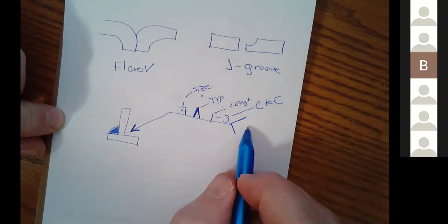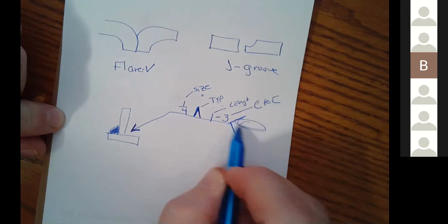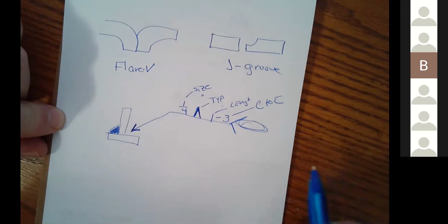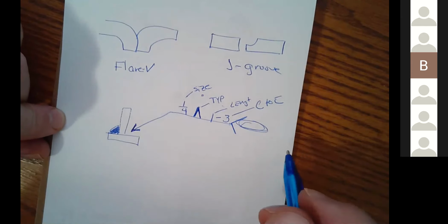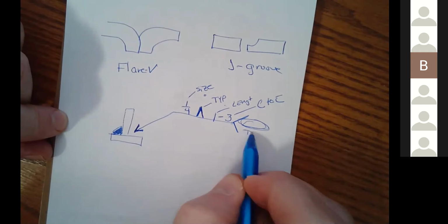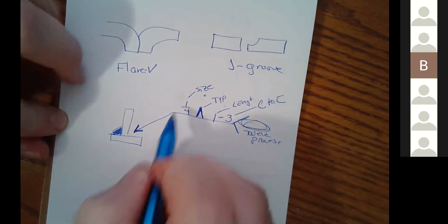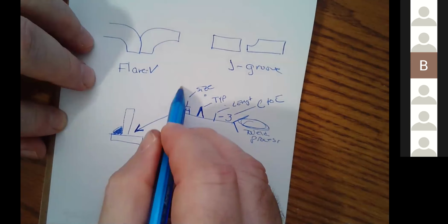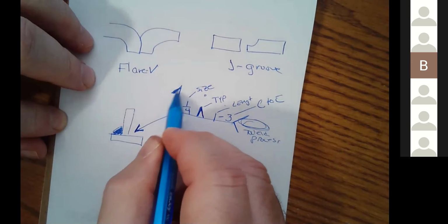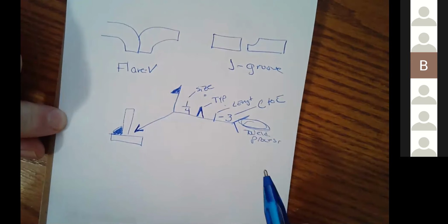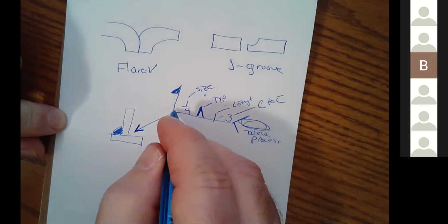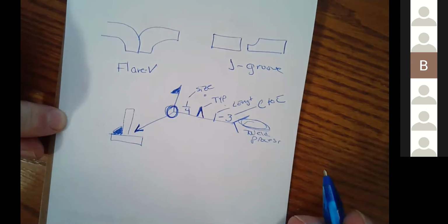Okay, and what typically goes in the little flag area? Extra information. The type of weld that you're doing. The process. Weld process. Okay, what if we have this little flag here? What does this guy mean? In the field weld. Weld it in the field. And then what does this guy right here mean? All around. All the way around it.